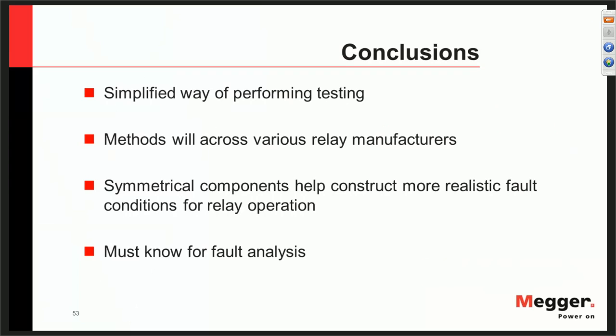Going to the conclusions now. With the whole presentation, you have understood the idea of sequence components, and you have seen that it's a simplified way of performing testing. It will be constant across all relay manufacturers. Doesn't matter who the relay manufacturer is, because this is a logic or a theory that is applied across the universe. It's more realistic. It will help you create more realistic fault conditions, and also it is a must-know for fault analysis. If you are a relay settings engineer, you need to know the idea of sequence components.